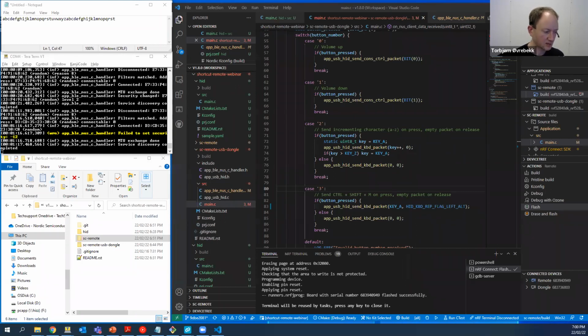So in this case, it's a bit about making a good demo as well, not just making an optimized product. But as I write in the README, I would like to have a separate branch of this project that does Bluetooth HID directly. So you can just communicate directly with hosts that support Bluetooth HID, which includes most Windows devices and, yeah, mobile phones as well. So that should definitely be possible. You basically have to start out with one of the Bluetooth HID examples in nRF Connect SDK instead of using the USB HID and UART examples that I used.